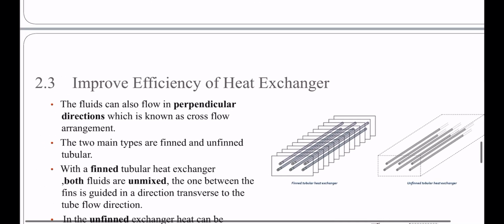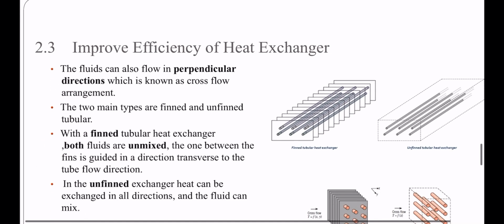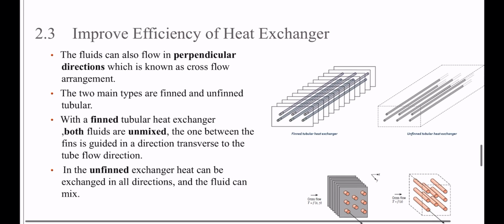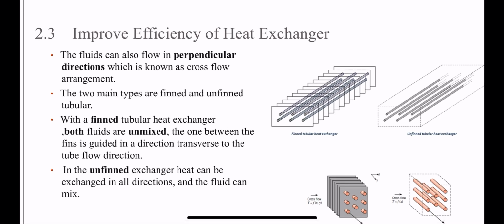So how do we improve the performance of those heat exchangers? How do you improve the efficiency of heat exchangers? The fluid can flow in perpendicular directions, which is known as cross-flow arrangement. We talked about counterflow and parallel flow, and this is the perpendicular direction, which we call cross-flow.